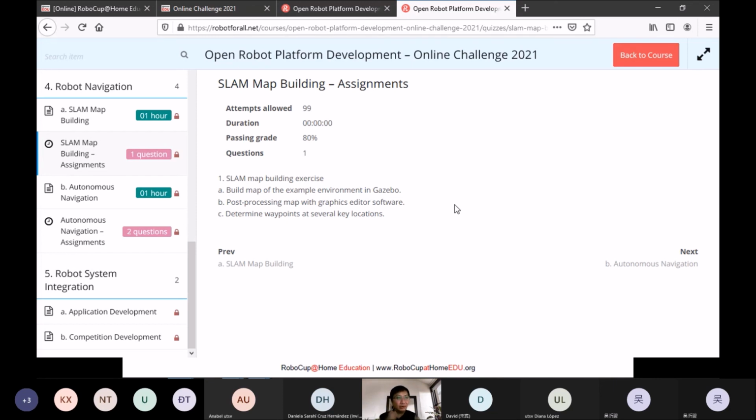So in order to avoid that, try to enclose your map by completing your scanning in one circle to make sure everything is covered. Even if you have a door that is open, try to cover the door area as well. If you don't want the robot to go out through the door, you just want to know there's an opening there, but the robot is not going to do anything outside.